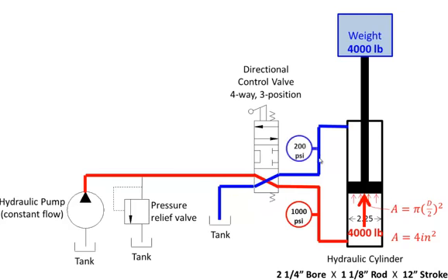Or maybe the piping is too small, so that pressure has to build to overcome the restriction caused by the piping being too small. What would that do to the ability to lift a weight? Well, this 200 psi of pressure would be acting downward on this piston, but it wouldn't be acting on the entire area of the piston, just on this, because the rod is taking up some of the space.